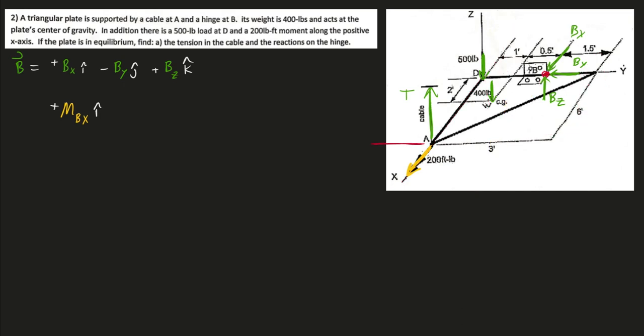Now let's say I also try to rotate the plate in this manner. These 2 forces would want to cause a rotation in the z direction. And of course, the hinge would not want to allow this. The hinge would fight against my 2 forces. So in this case, the hinge is putting a moment in the negative z direction to fight against this red rotation that I'm trying to cause. So this is just to say that this hinge here will also create a couple moment in the z direction. And just in my picture here, I'm assuming it to be in the negative z direction. That's okay, that direction's just an assumption, but I'll just stick with that, the negative z direction.